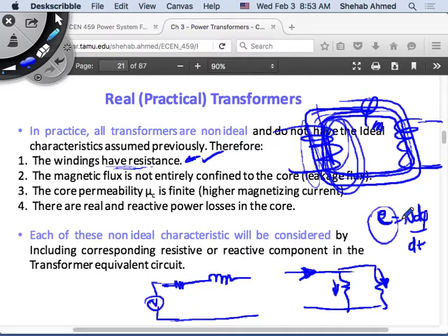So it's a component that has to be placed in parallel with my output, because the voltage across it is what I have across the winding. So the voltage across this specific representation of the flux flowing in this magnetic circuit has to be a parallel component, because the voltage across it is this voltage that I have developed, E1, on the primary side of the transformer.